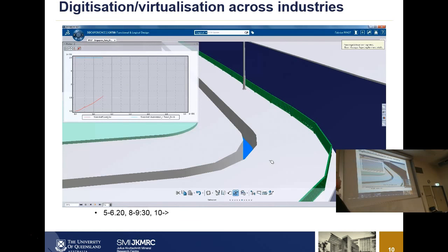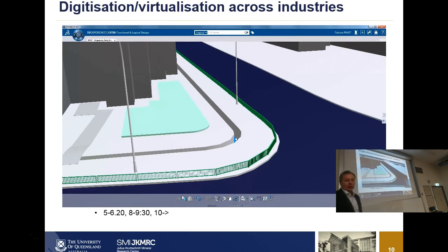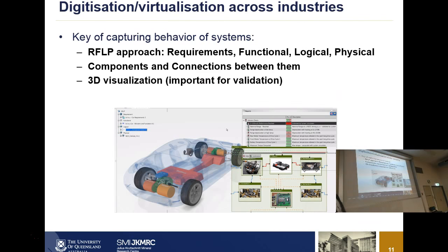The key here, and later on, actually I won't show that now, but later on what they do is they say, okay, what happens in a 1 in 100 year rain event? They find that it floods again or gets very close to flooding, so they simply just go to the pump station, and rather than having 3 or 4 parallel pumps, they increase the number of pumps to 6. And now they've got a design for that system given variations in that block. So if they put a new building in the block, they might run a new model. Okay, let's just jump ahead from that.